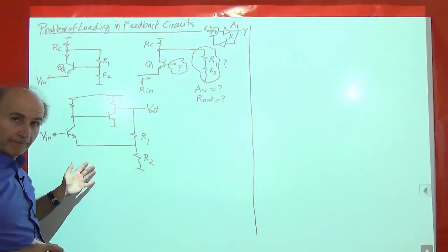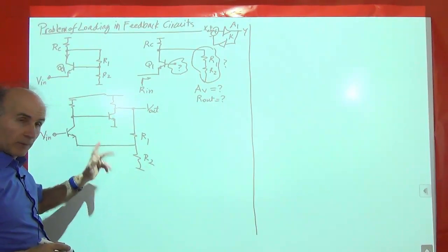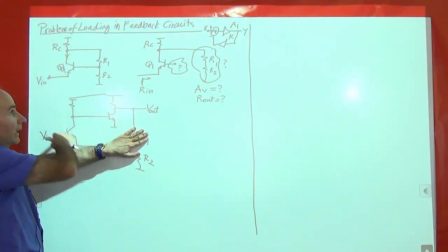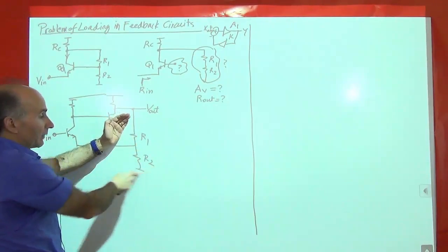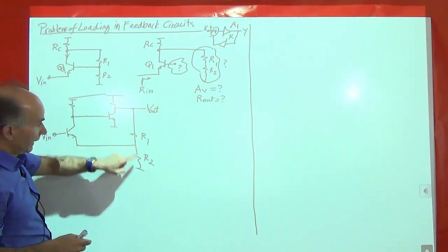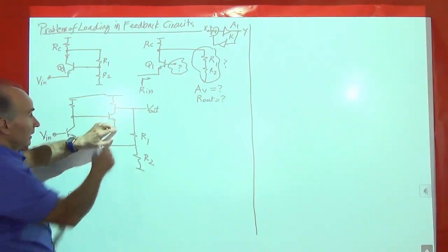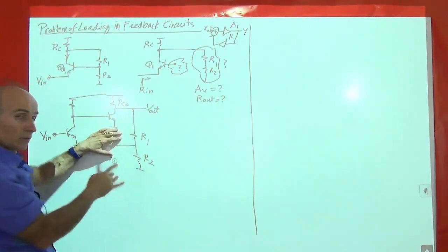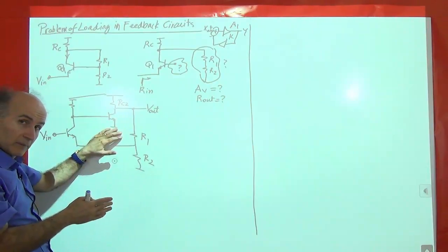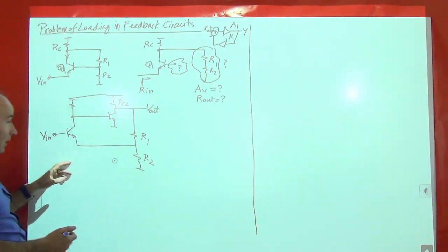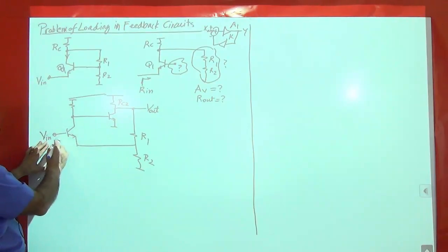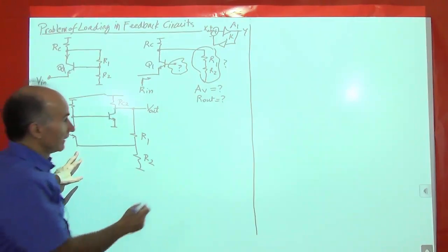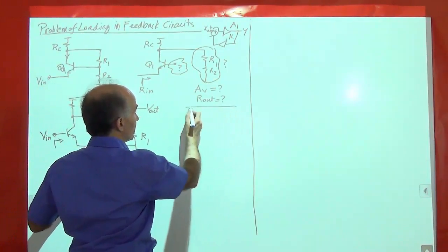Well, we saw this before. Now, when I open the loop, so let's say I cut the loop here, and I say, okay, now this is my amplifier A1, and this is my K, right? Well, okay, so obviously K again is loading the output here. So this is RC2. Now we have something here loading RC2. We don't exactly know what. And the other situation is that this input impedance for the open loop circuit is not just R pi. So let's go and draw the open loop circuit.